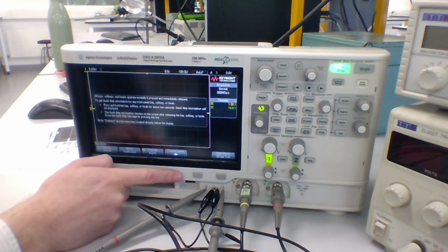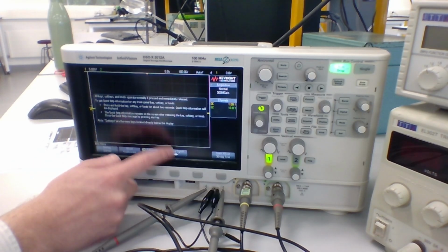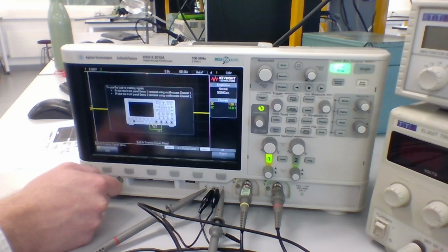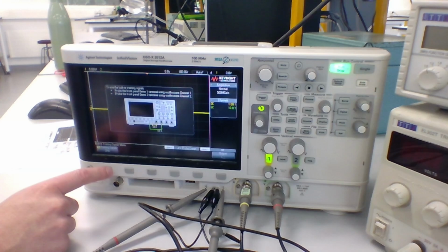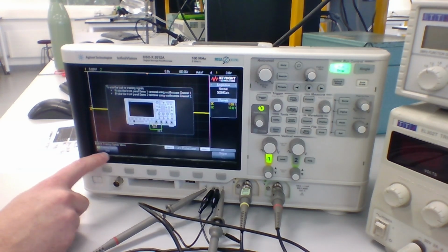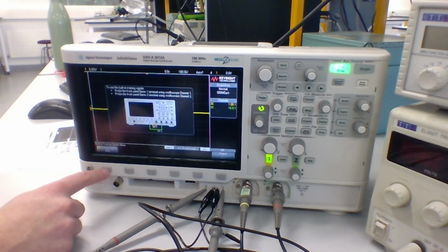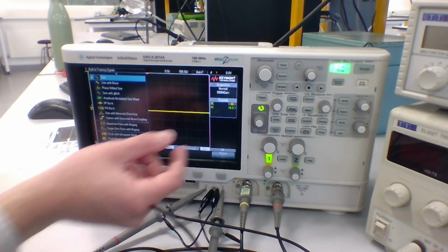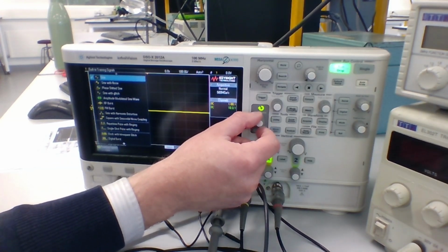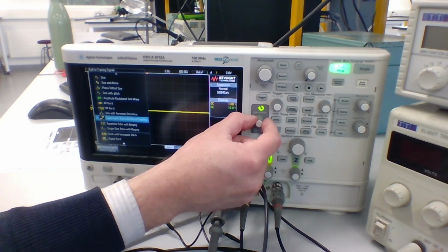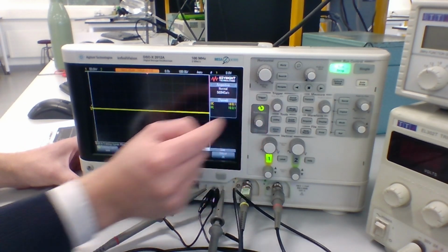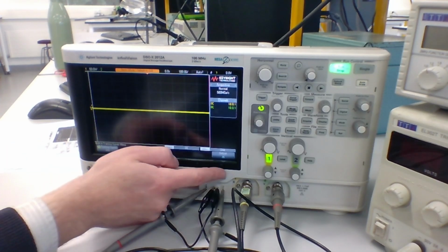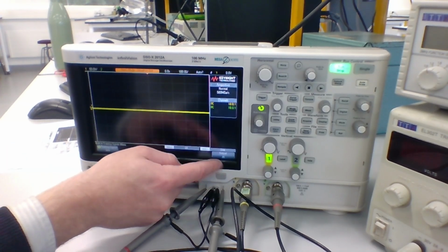Underneath these are what we call the soft keys. We'll press the soft key that corresponds to training signals. It will tell us something about what these signals are and some setup for those. And we want to have training signal, in this case being sine, which it is. If we wanted to change that, we could press that key and then use this knob here and rotate through and select different signals here. So we go up to sine and then we press this to select. We then press output to turn that output on.